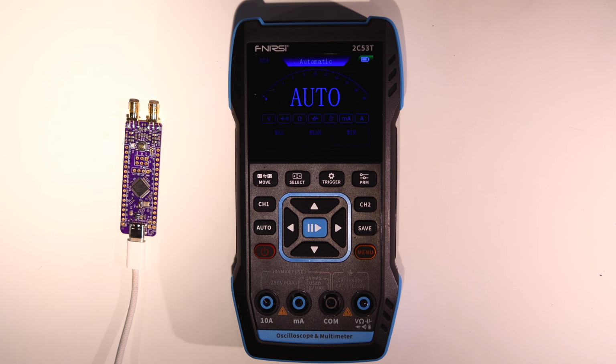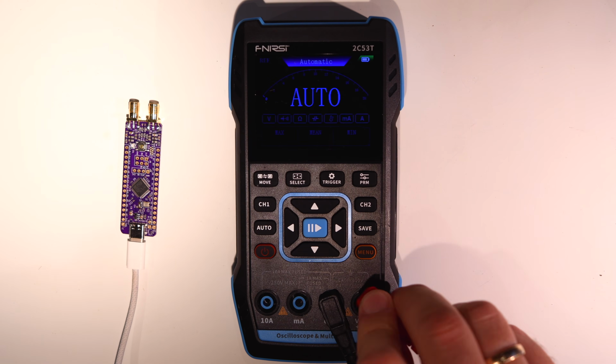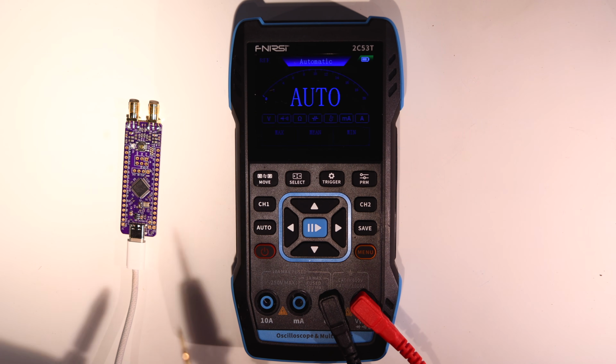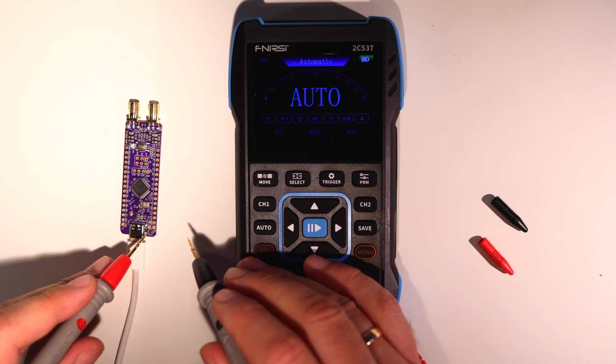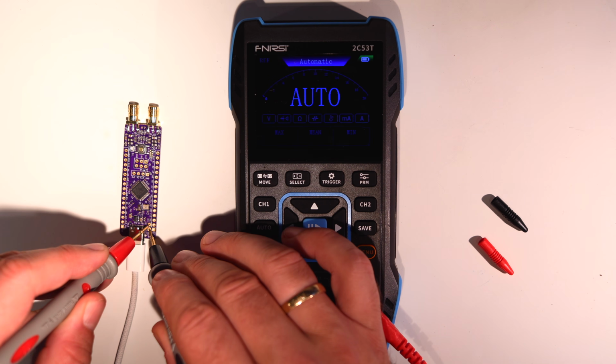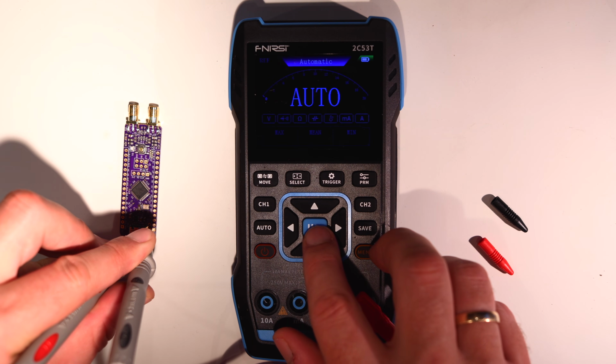I haven't used STM32s a lot in my designs for no particular reason, but they're really easy to get running with not much more than a crystal, a few caps, and a reset pull-up. I hope I didn't say that too fast though, as I haven't even checked the voltages yet, so that's probably a good first step before we throw some firmware on it.